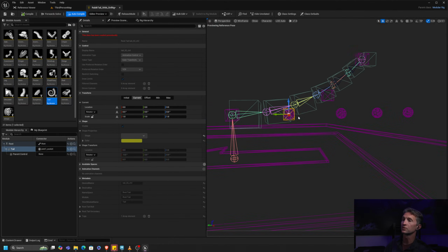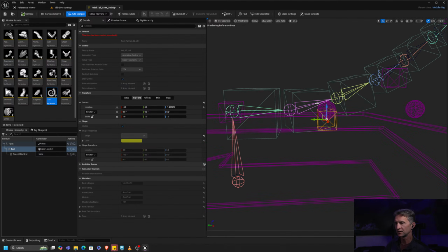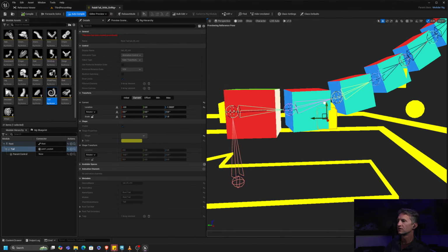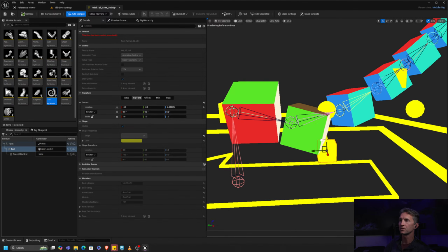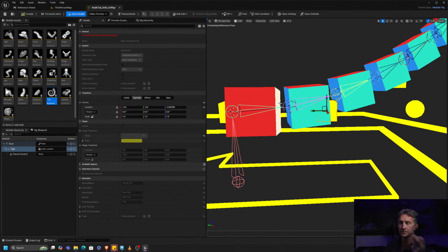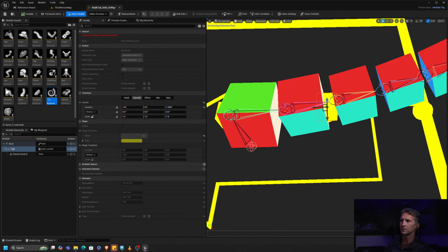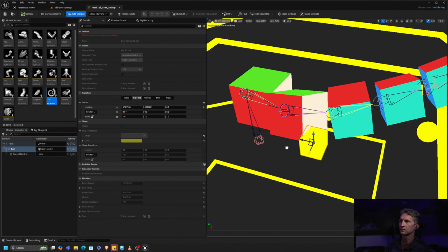What I wanted to see, specifically what I was looking for, by the way, is I wanted to see, yeah, okay, we can see it, and we know we have the wrong axis. So the issue or the challenge still exists here, except what's happening is the axis is off. What I was curious about was, remember when we moved this control in a normal spline IK, the base joint was countering? All this is showing us is that same thing exists even in this tail, but in this case I have my axes wrong. Either my joint orients are messed up or I've just specified them incorrectly. And what's happening is the man, yeah, it's totally odd.